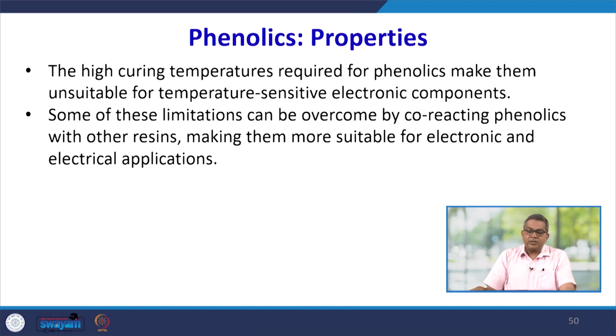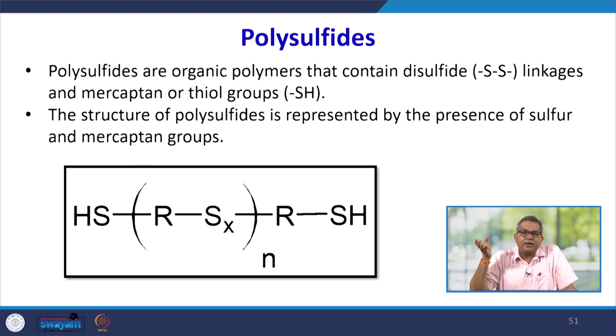The high curing temperature sometimes required for phenolics makes them unsuitable for temperature sensitive electronic components, and some of these limitations can be overcome by co-reacting phenolics with other resins, making them more suitable for electronic and electrical applications. Let's talk about the polysulfides.